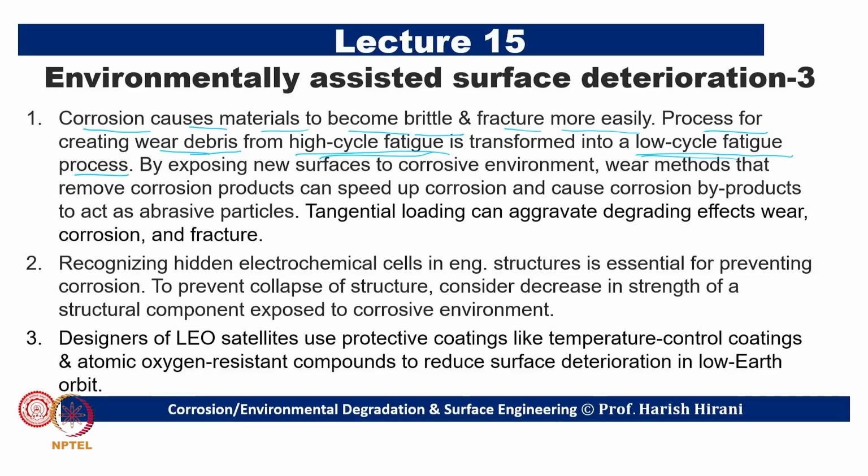That is what has been written here. Exposing a new surface to the corrosive environment happens automatically, because wear is associated with fracture and there is removal of debris from the surface. Naturally, when the debris gets removed, a new surface is exposed to the environment and will get corroded.